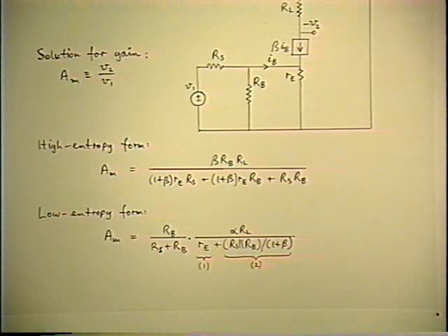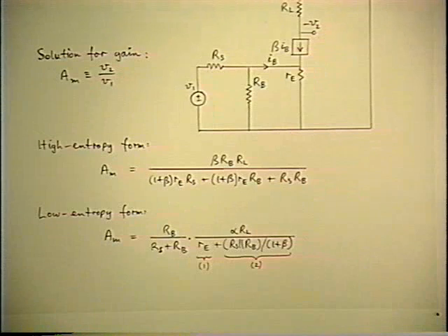So it represents a series parallel combination. And the thing you know about that is resistances in series are dominated by whichever one is larger. Resistances in parallel are dominated by whichever one is smaller. So if the numbers that you've chosen initially are not satisfactory, then you have a much better idea of how to go back and change them when you have the grouping already arranged in series parallel combinations, because you know which ones will be more important in the result.